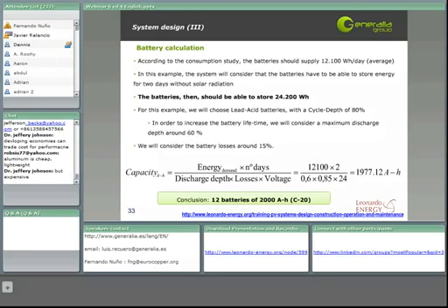We can consider that this is conservative, as in fact if we have introduced the consideration of getting the batteries functioning for 3 days, in fact, the battery will be discharged in a longer period than 20 hours, but then we will get even more energy from the batteries than the one that has been calculated. So it is better for us.